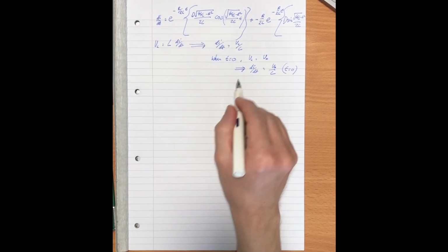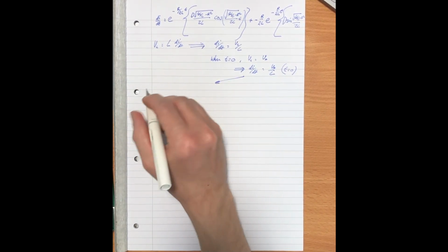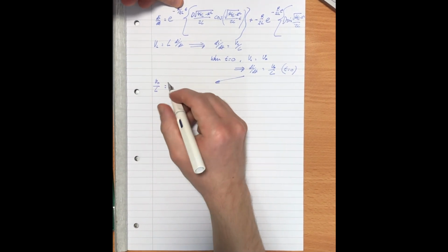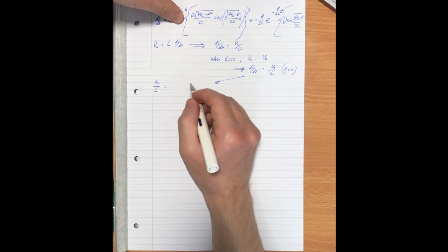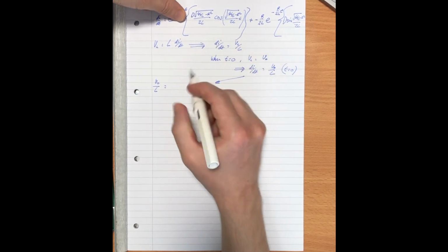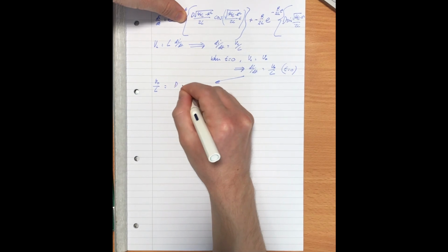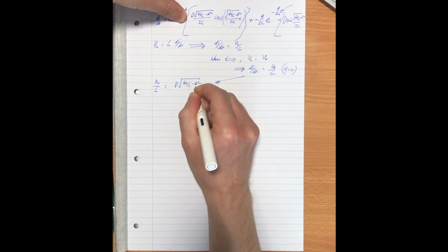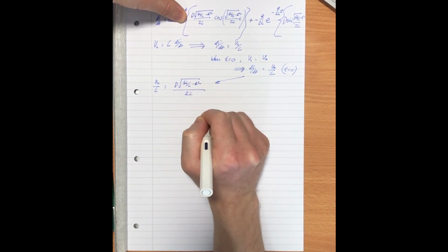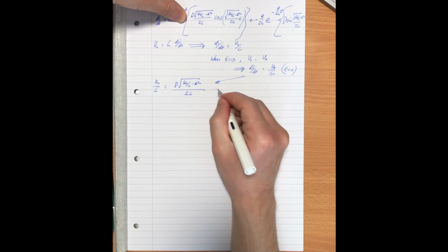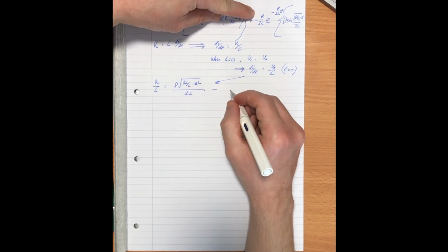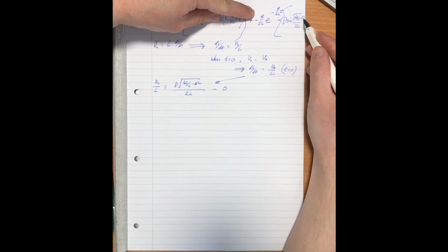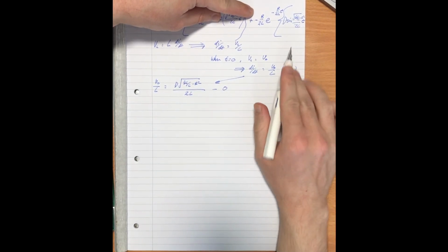Yeah? So if we make that substitution over here, we can say that V naught on L equals, when t equals 0, e to the naught is 1, cos 0 is 1, so that's going to be D root 4L on C minus R squared on 2L, cos 0 is 1, yeah, minus 0, because D sine, there should be a t there, that whole thing is going to be 0.